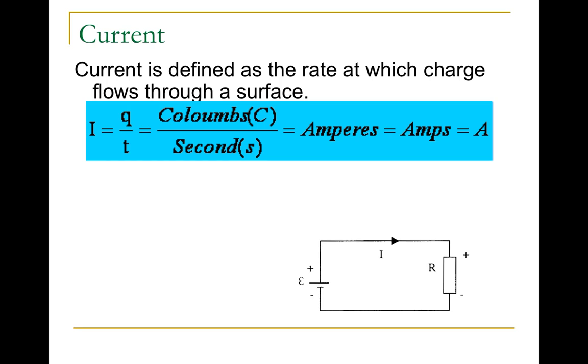At the bottom of the screen you see a circuit. Now remember, we did briefly talk about the flow of conventional current, which is following the flow of positive charges. That's what you're seeing in this diagram. So you see that arrow at the top that's pointed to the right, so you see the flow in a clockwise direction, but that has gone from the positive side of the battery up to the right and then down through the resistor. We are going to follow the flow of negative charges, those electrons. So that means in this circuit, when we analyze it, the current would flow counterclockwise.